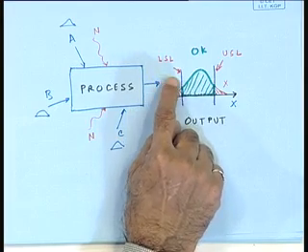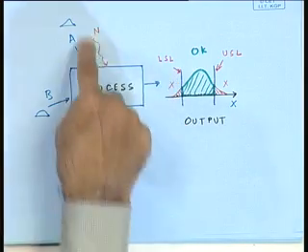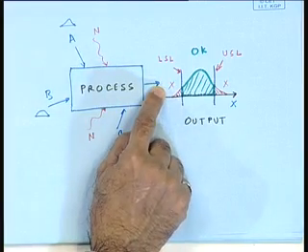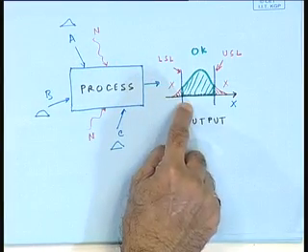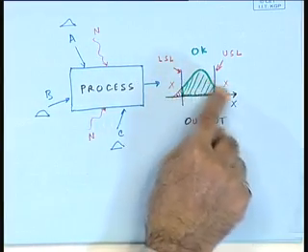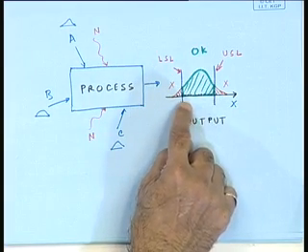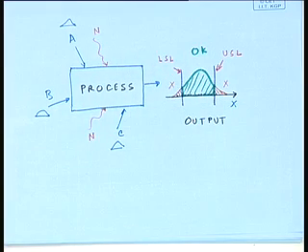If it turns out that you've got a lot of assignable factors there, then of course you go back and do an investigation. If you've taken care of the assignable factors, then you look at the spread of the process, because that is now the natural variation of the process. If that goes either above or below what we call the tolerance, you have to then play with the sigma of the process. And this again, like I said, can be done. This is the overall variability of the process. And one great way to tackle that is to apply design of experiments.